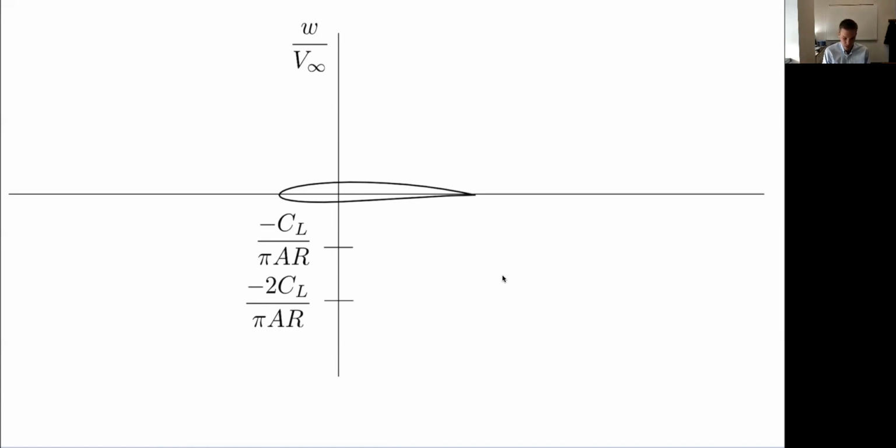But what we saw, this was actually exactly what we computed, right? We took this model here, we calculated the influence of a trailing vortex and integrated to compute all the trailing vortices. Notice actually that we never talked about the bound vortex. And now we're going to discuss if that's actually problematic or not, because we didn't include that. If we had a very simple case, this planar wing, the bound vortex would induce no velocity on itself because the center of the bound vortex would pass through this point. So that's one way to justify it.